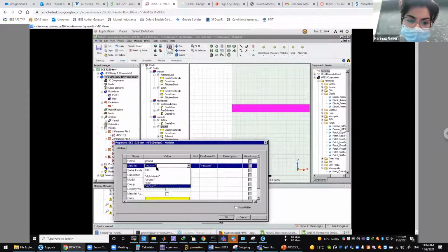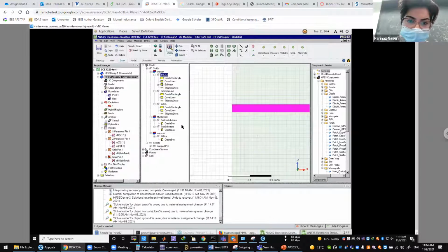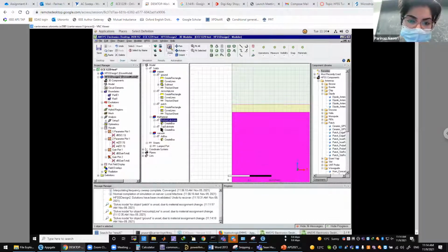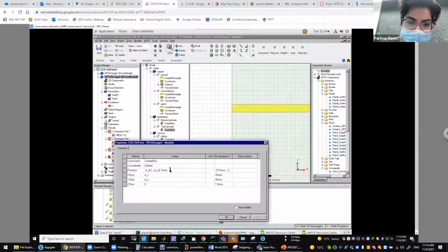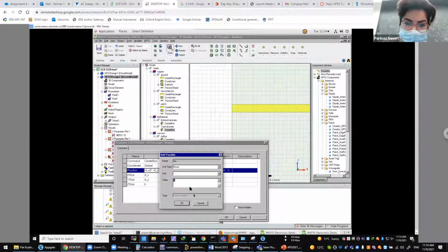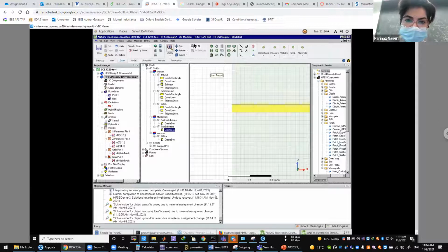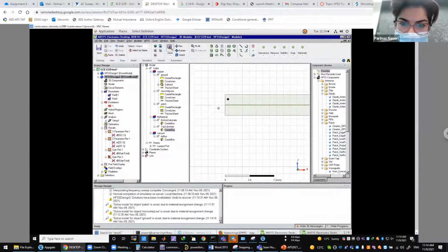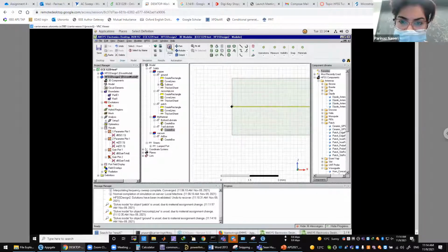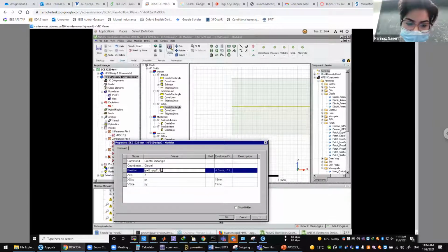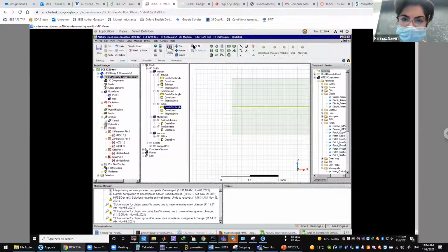I'm going to add copper to the ground. I'll show you how it looks. So the bottom substrate, let's assume, is correct, and we're going to adjust the top layer. HM is the thickness of metallization. So now you can see that the second layer starts from after the metallization to the top. The patch again, you want it to start from HM. So it moves up here.